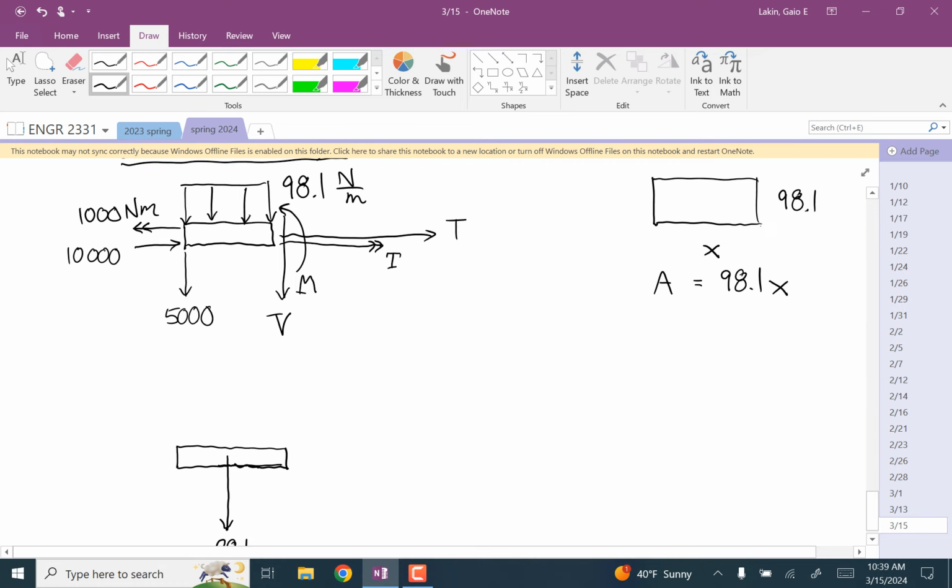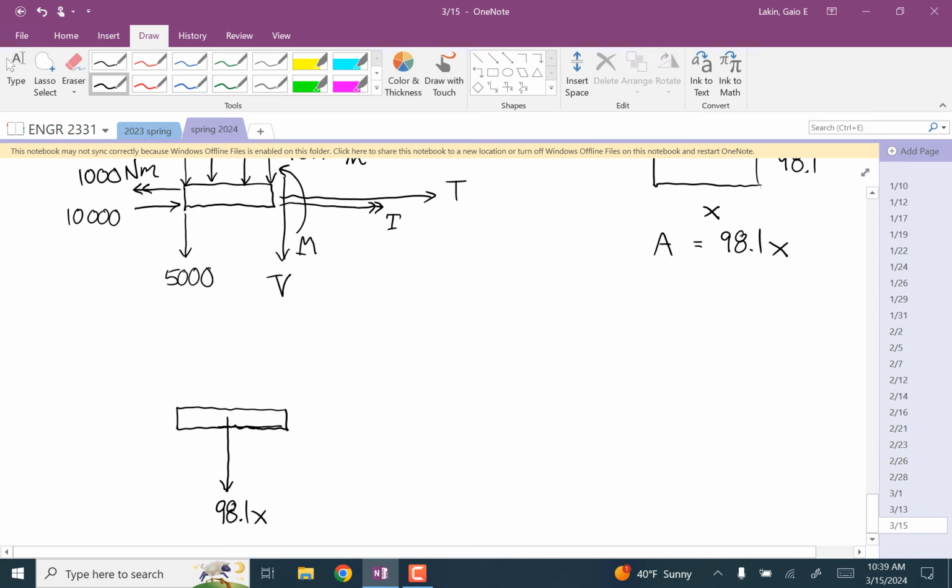You can see how, I mean, I pulled these numbers out of thin air, but you can see these are kind of in the ballpark of what seems reasonable for external loads. We actually calculated a reasonable mass, and you can see how much that weight force is going to be dwarfed by those other forces. That's why in a lot of cases you end up just leaving the weight out of this stuff. It just doesn't matter to any of the calculations.